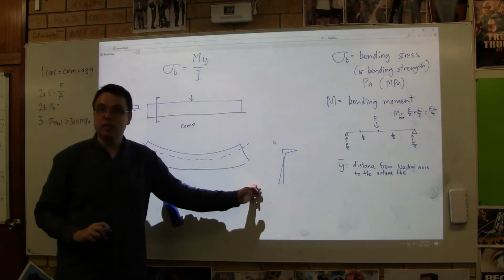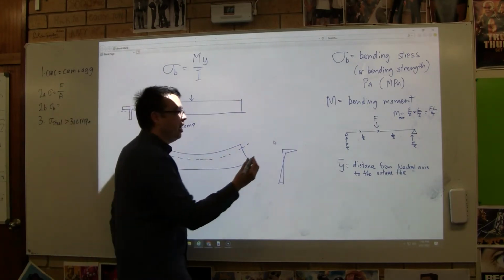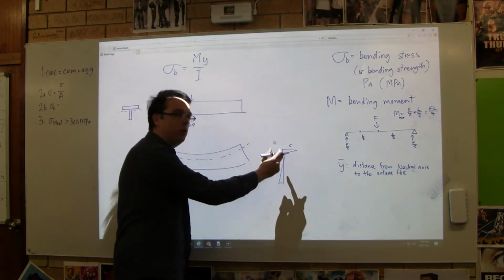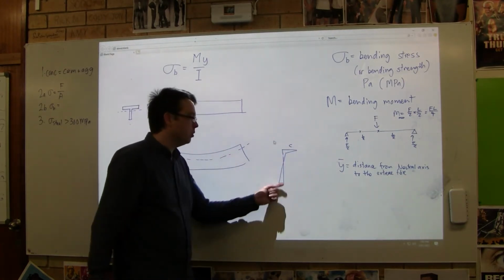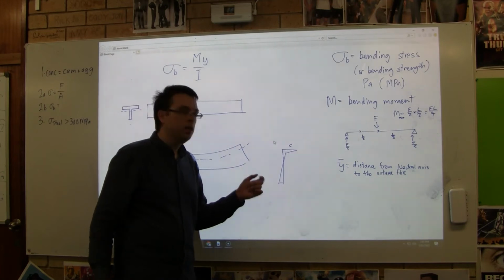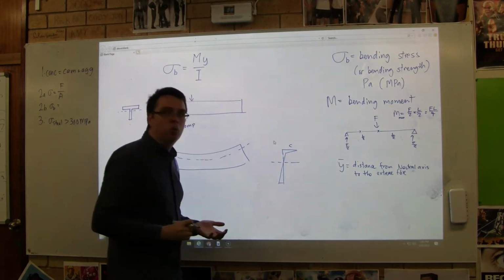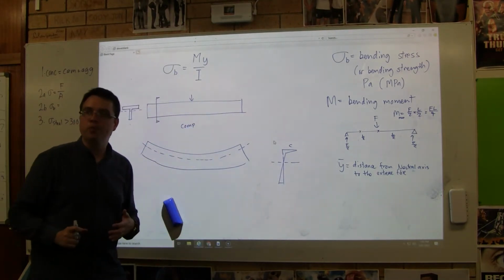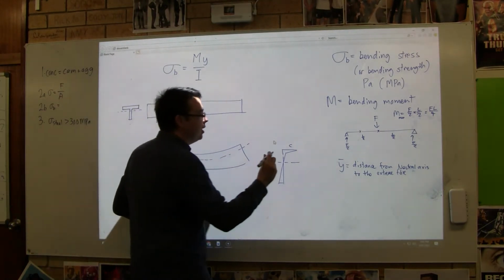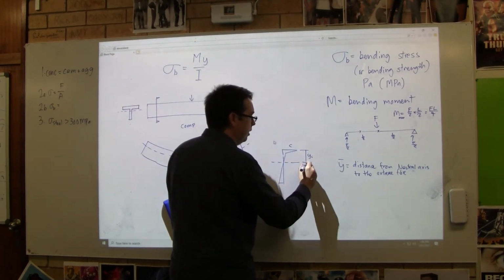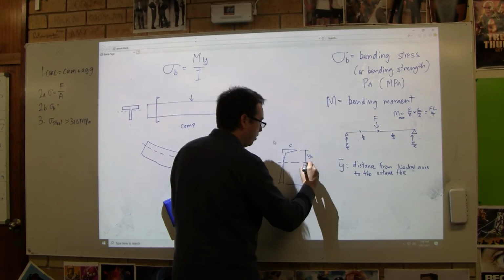In this case, the diagram looks something like this. You have stacks of compression up the top, but see how the area in the compression zone has to be equal to the area of the tension zone? Yeah? So do you see how in this situation, the area is about equal, but a very different shape. Yeah, so in this case here, the distance from the YC is very different to the YT.